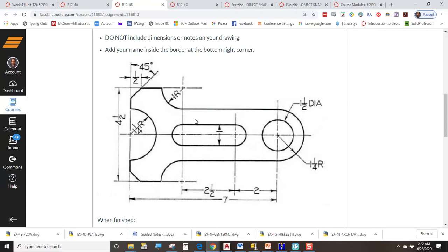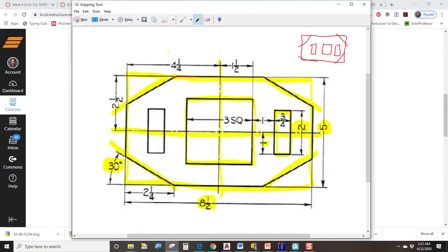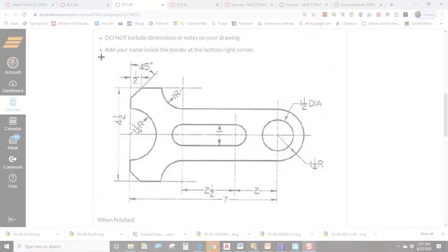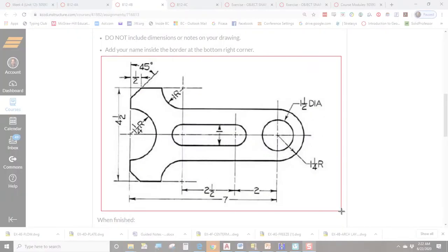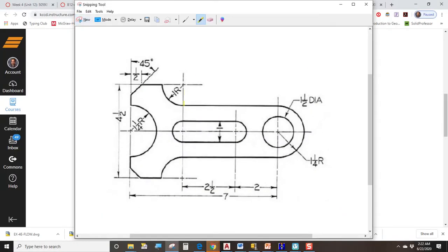Now, this one here is a little bit trickier. No doubt, this is a little bit trickier. Okay, so again, though, I think the best thing you could possibly do is I see center lines. And when I see center lines, here's what I think. I think that's my skeleton. So if I were you, I would make a horizontal center line and then make a vertical center line on the right side toward the right end of the center line.